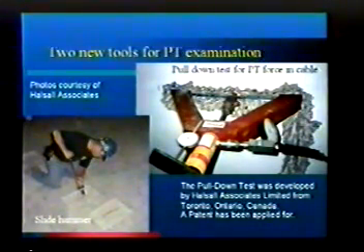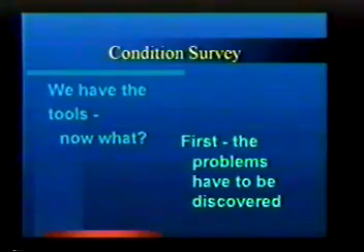Here's the device that they can pull on the PT cable, and depending on how much it deflects, it can be correlated to how much force is in the PT cable. Okay, so a couple of new devices.